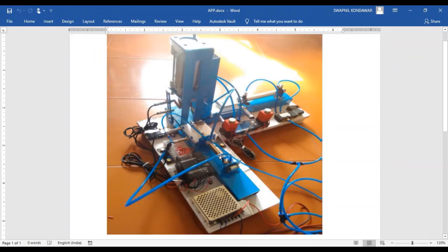This is a pneumatic system. You can see there are three pneumatic cylinders, and here is the product. Actually this is electro-pneumatic because you can see there are sensors, but the same system can be rebuilt as pneumatic. The logic remains the same whether it is electro-pneumatic, pneumatic or hydraulic. To understand this application, we push one product at a time to this location, then we stamp that product, then this stamping cylinder goes back, and then this pushing cylinder pushes the part out. So this is the simple application.